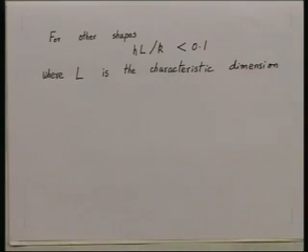L is a measure of the distance, the maximum distance that heat has to flow within the body. Why is it? So, therefore, for a slab it is half the width, because heat flows from the center line outwards towards the two faces. For the cylinder, why is it the radius? Because from the center axis heat is flowing outwards towards the faces, or inwards from, if the body is heating up, inwards from the circular face towards the center line.